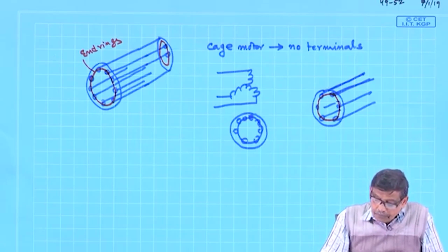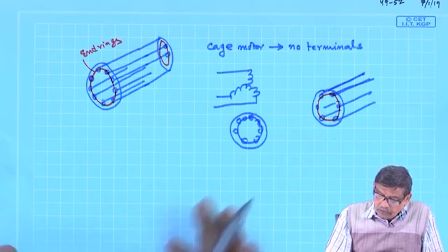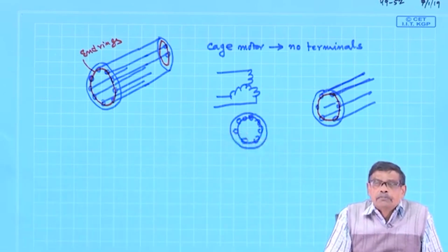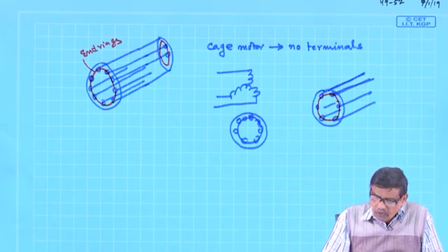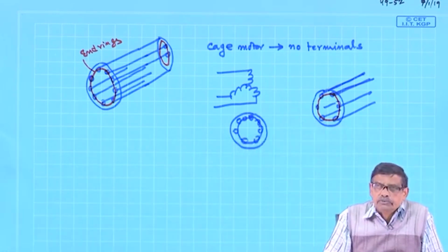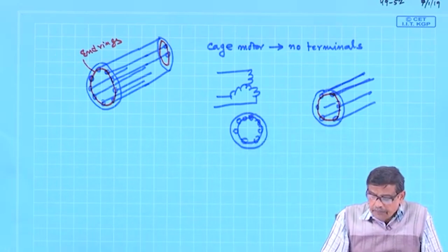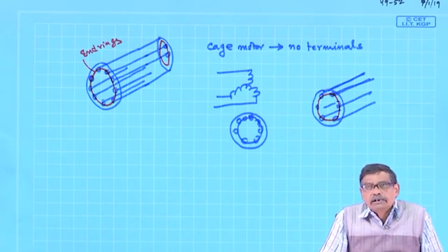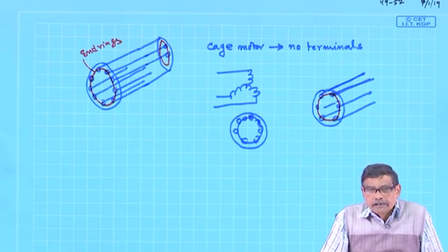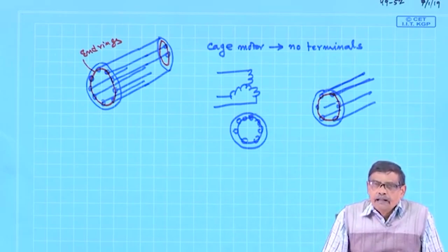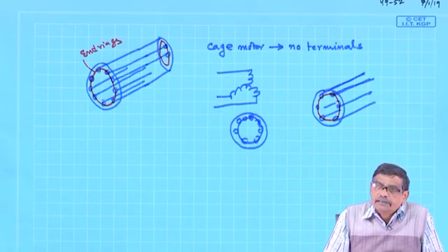The important point is the rotor should produce the same number of poles as that of the stator, no matter what kind of winding you use. For example, you could have a 3-phase induction motor whose stator is wound for 3-phase, and the rotor is wound for 2-phase with 2 slip rings, etc., and things will run, provided these 2 windings are wound for the same number of poles.